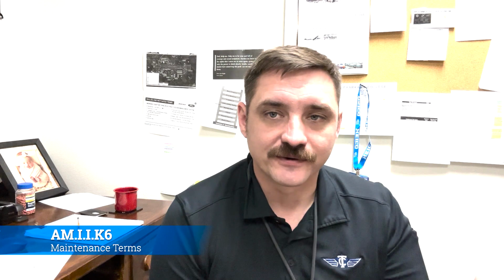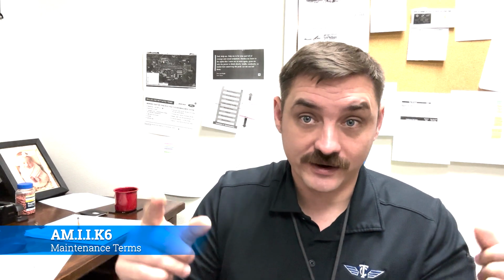And as time progressed and as technology progressed, they made engines more and more efficient. I think we're on ETOPS 360 now, which means that basically you can fly just about anywhere in the world direct, because the plane can fly, well, not necessarily indefinitely, but for 360 minutes straight with just one engine and be okay. That opens up the world to a lot of very cool and interesting places, whereas before maybe they couldn't get there. It would be very hard to land in, say, the Maldives under ETOPS 60, because I don't think there was ever a plane that could actually land there within a 1 hour flight on one engine.